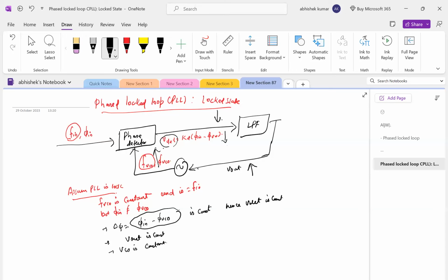So in this way we are saying that if noise is increasing, then the loop acts to reduce its gain back, and in that way it is stable, because this is the feedback. V out increases slightly and V difference decreases slightly.